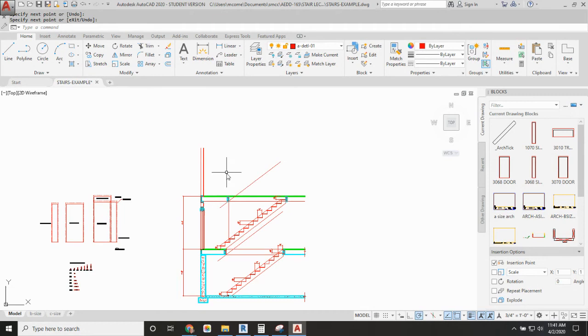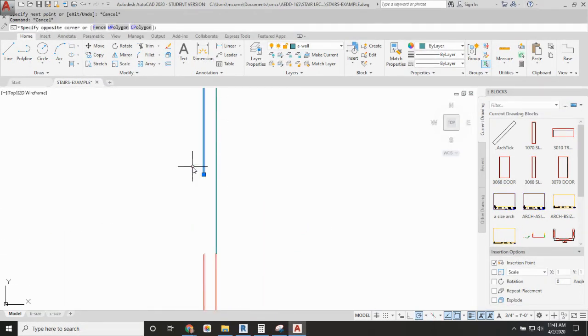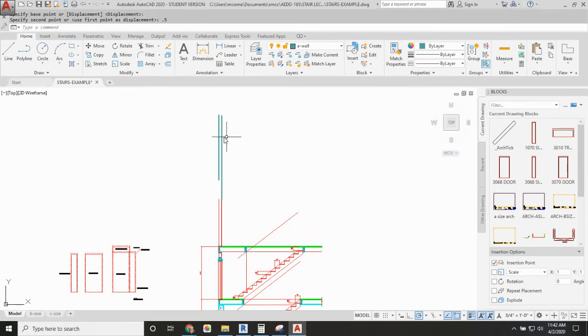So how does this look in plan? Once you have generated the correct dimensions for your section, you can go back and put that information in your plan by projecting it. So if I were to draw using the wall tool here and draw my exterior walls up here, let's just get... We don't actually need that. We'll draw another line for the inside of the wall. That in 0.5 inches. Okay, so that's representing the exterior wall.